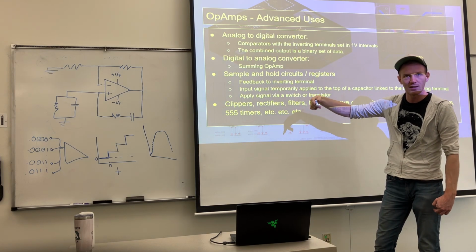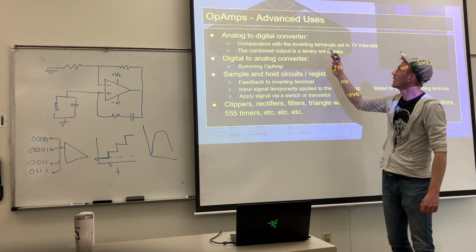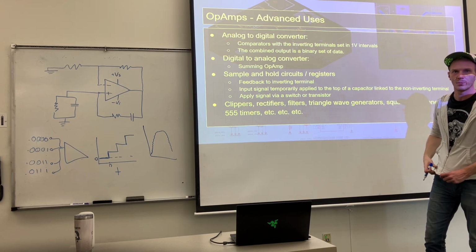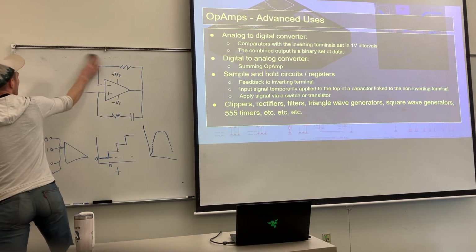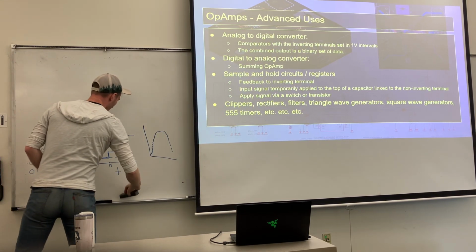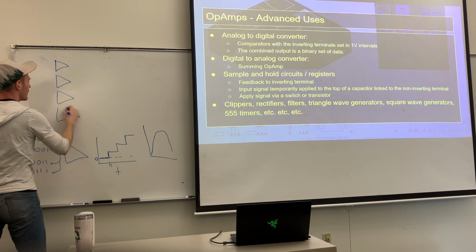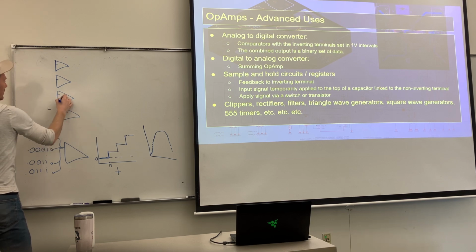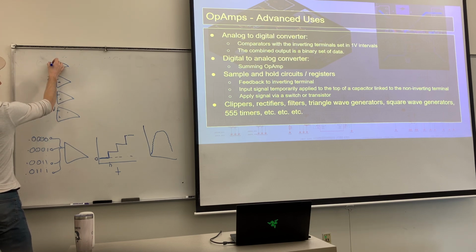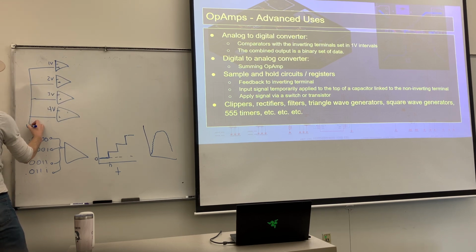Now we want binary digits from our analog data. So this is going back to comparators, right? This is basically the reverse operation of what we just did. But imagine we have 4 comparators. They're not hooked up to any sort of feedback. All they're doing is comparing in and out. You've got negative, negative, negative, positive, positive, positive, positive. You've got 4 volts, 3 volts, 2 volts, 1 volt, and all of the non-inverting terminals are hooked up to something, V signal.